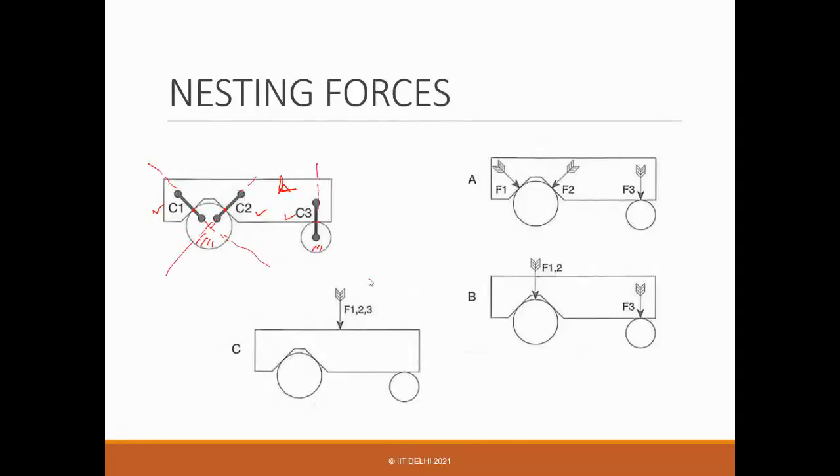So these are three contacts, and as long as these contacts are made, body L with respect to the reference plane, or those two pins, will be accurately placed. But you have to make sure that they are in contact all the time, because suppose there is a movement this way, or you apply a force like this, there will be no contact. So it will move away. But as long as there is a force, I'm just putting a random force, and placement is such that C1, C2, and C3 is always positive, then it works.